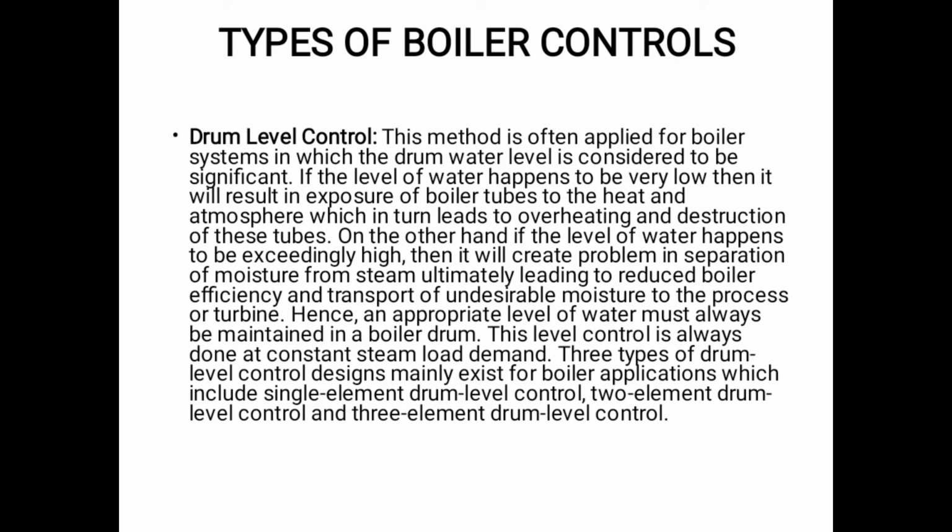Today our topic of discussion was the boiler control system and how to control the boiler drum level. So boiler drum level is very important. As you know, in the boiler it has a very important and crucial role. If the level of the boiler increases, then our carryover will increase, and this will harm our steam turbine or superheater, and it will ultimately reduce our efficiency. So how do we control our boiler drum level?